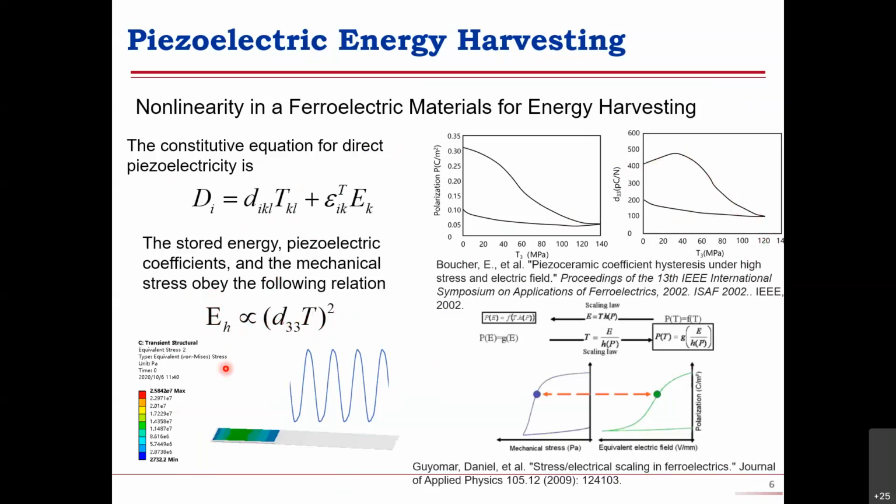And I have analyzed a piezo ceramic attached to a cantilever beam, and when this cantilever beam vibrates at 1g acceleration and at about 40 hertz, we can see there is a small nonlinearity in the current output.